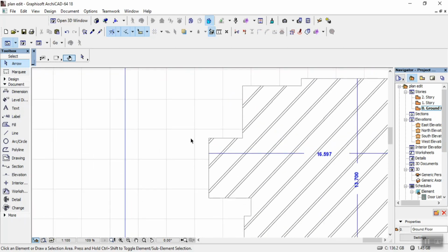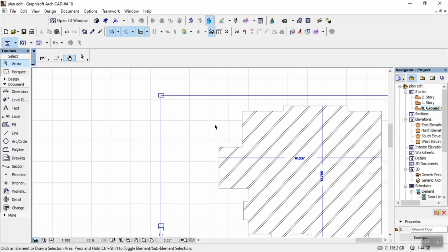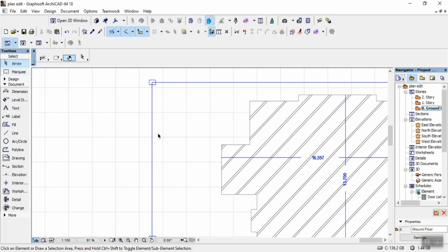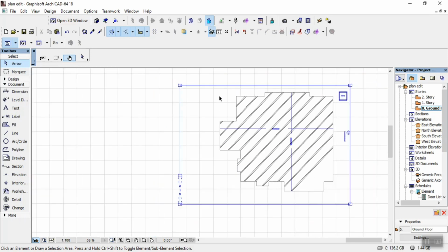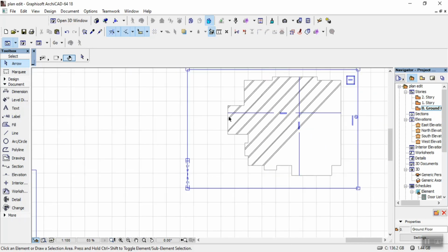So the next thing is my soakaway. Let me see. Okay, septic tank. I'll come here. I want to place the soakaway here. Assuming there's a security house here, the soakaway has to be here. But these days we build soakaways that are motorable. Our cars drive on them. So you can place the soakaway anywhere in this compound that you think is okay. You can place it here or you can place it here. The car is going to drive on it. All you just need to do is make sure the reinforcement is okay, then you deck it as a slab.